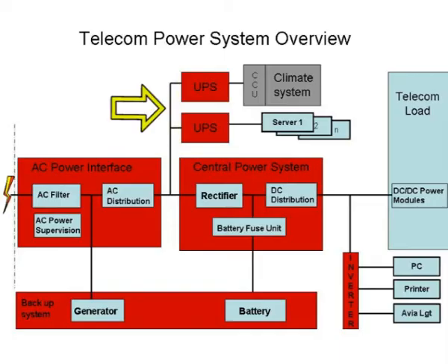The main characteristics of a UPS, that's an uninterrupted power supply, are: the UPS takes the AC from the mains and transforms it into reliable and more stable AC by means of an AC-DC-AC conversion process. During this period, it also charges its own batteries. During mains failure, it pulls DC power from its battery banks and converts it to AC.